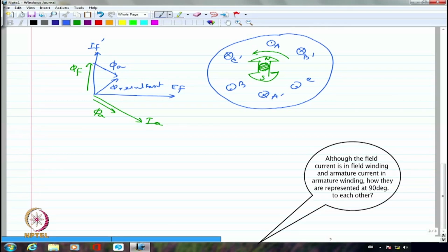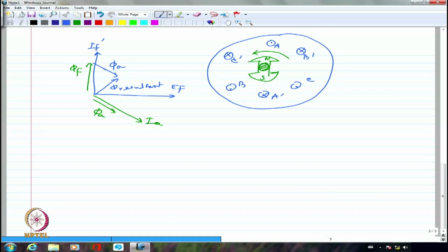See, if I am having IF here, it is inducing an EMF not in its own self, it is inducing in another winding. I am showing the other winding's induced EMF as though it is getting 90 degrees shifted because of d phi by dt. So sine and cosine, very clearly a 90 degrees shift. So this is the induced EMF in the armature.